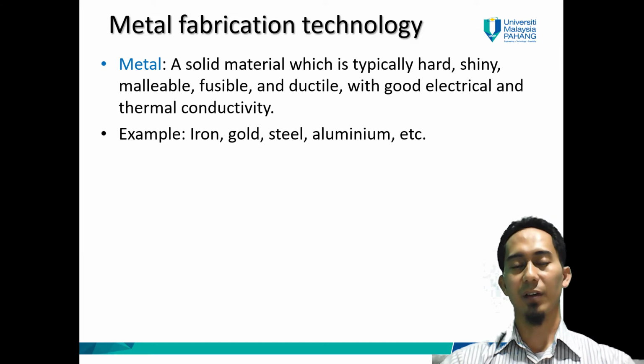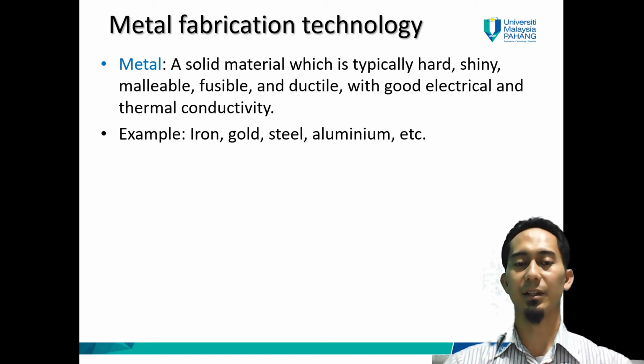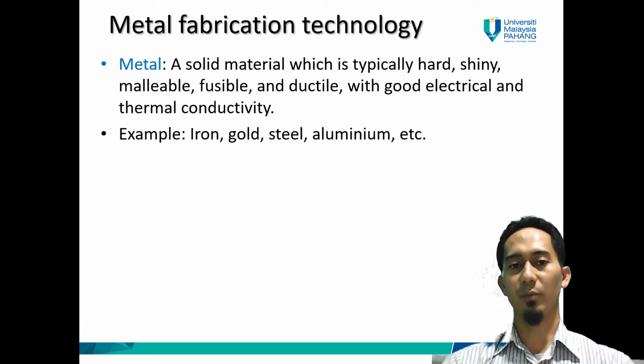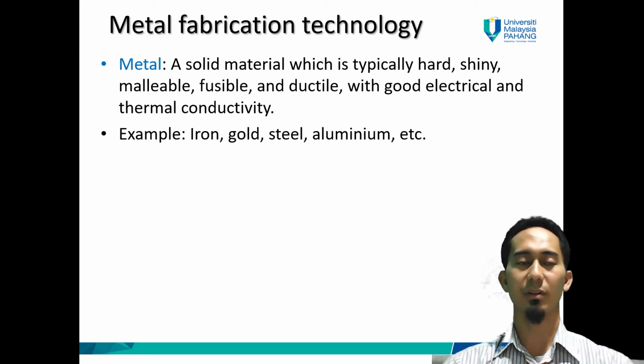Whereas for alloyed aluminum or aluminum alloys, we usually put in some other elements inside, such as magnesium or silicon or manganese, in order to mix with the main element, which is aluminum. When we mix them together, we try to make it stronger or make it more corrosion resistant, basically trying to improve the characteristics of that metal.